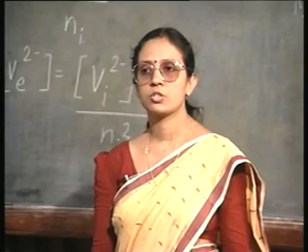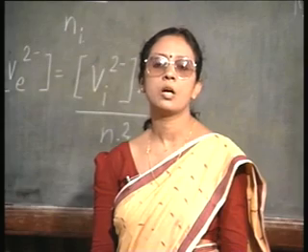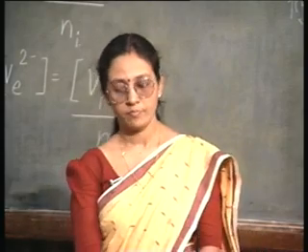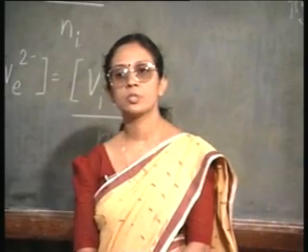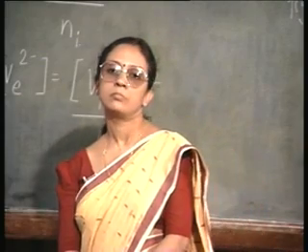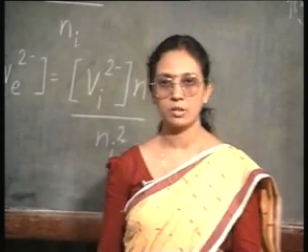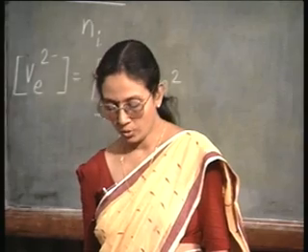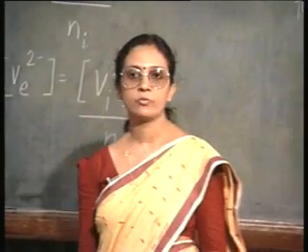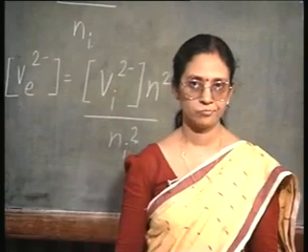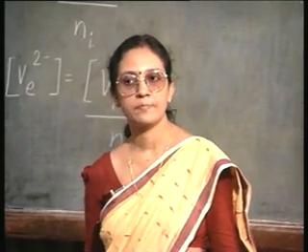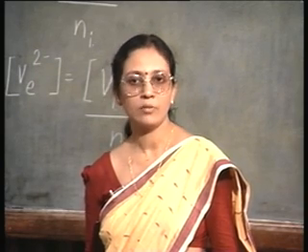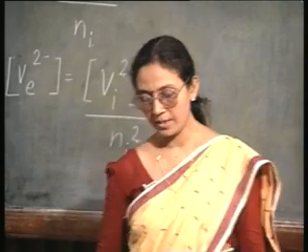Just like oxidation, even here you use a fused quartz tube, because that gives rise to the least contamination. And the temperature of diffusion is also approximately the same as the range of temperature for oxidation, 800 to 1200 degree centigrade. The question is the choice of dopant sources. Dopant sources can be solid, liquid, or gaseous.